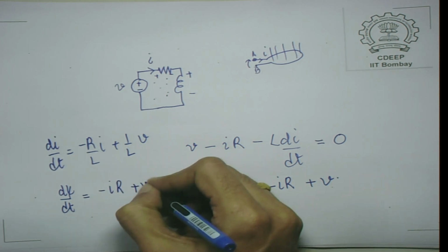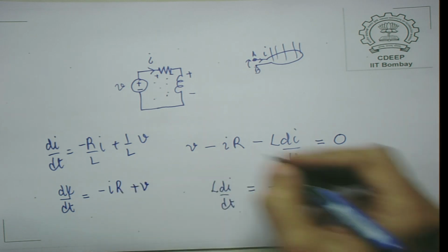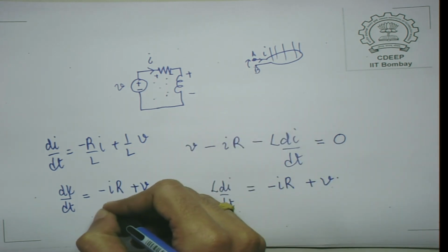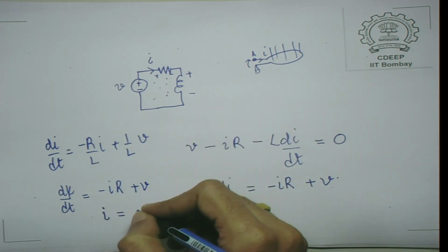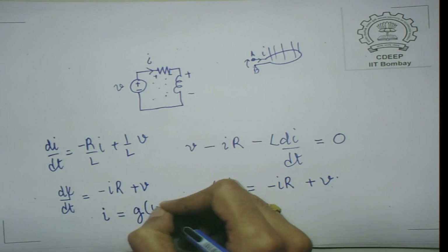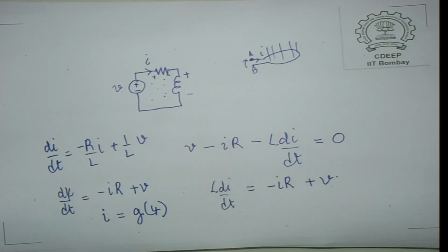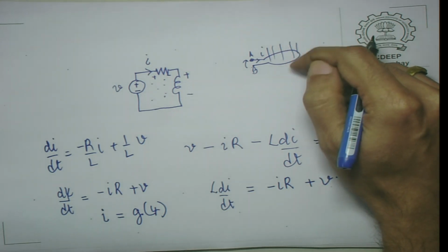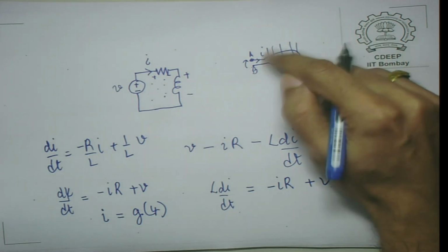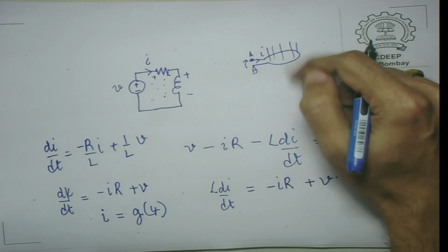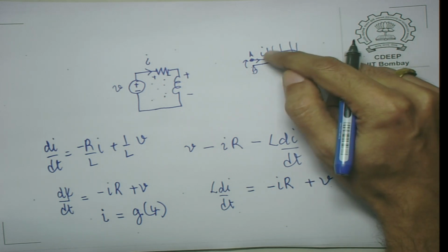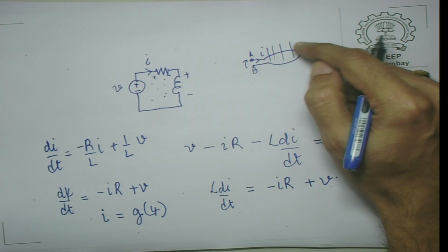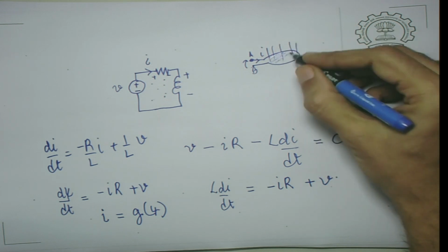plus V, and I is equal to a function of psi, or in other words psi is a function of I. So, this is another alternative way of writing it. Psi denotes the flux through this single coil of wire, or in case you have multiple turns, N into the amount of flux going through the wire. That flux, of course, is B dot ds integrated over this surface.